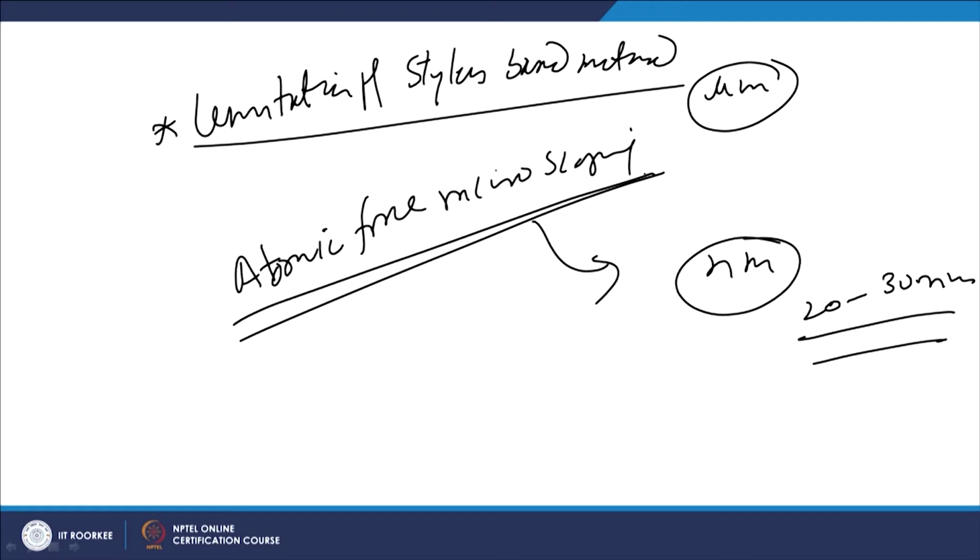Atomic force microscopy is used for measuring the surface roughness of a very small area with a very high level of surface finish. So, if we consider the limitations of the stylus method, the first one is that it is time consuming, and it needs to be repeated at a number of places for scanning a large area, because a smaller sampling length is used in one go.